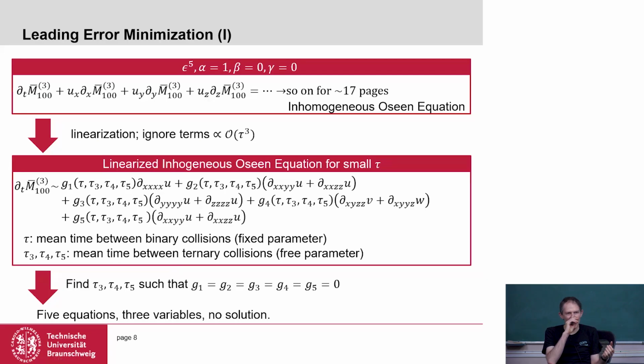And if to an Oseen equation you set zero initial and boundary conditions, this error term will actually disappear unless it is an inhomogeneous Oseen equation, which means that it has source terms which are related to the solution of the Navier-Stokes equation. Which is the case, and which is the reason why this is only second order accurate.